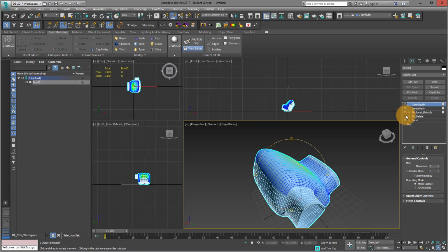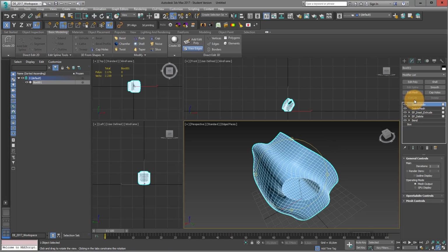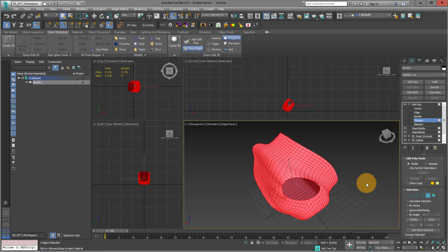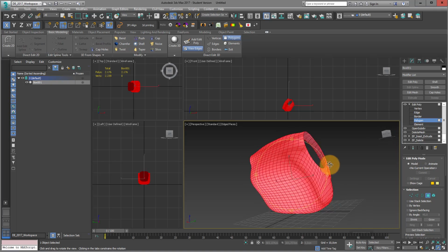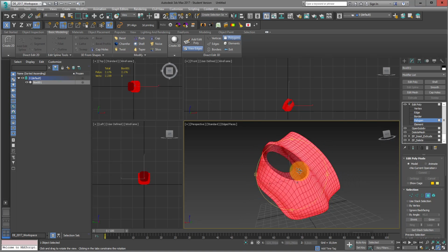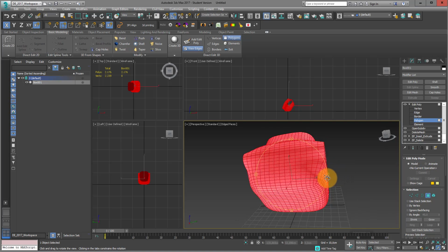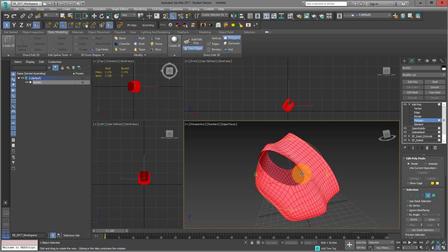And what you can also see is that it doesn't have a dimension. If I just go again into my and add another edit poly on top and go into the hierarchy of polygon and select all the polygons, then you can see that there is again these two kind of colors. So this is, for example, something you would not be able to use for 3D printing. So what you actually need, you have to add something like a shell. So it has a double surface, and there's something like a shell modifier, which is this one.